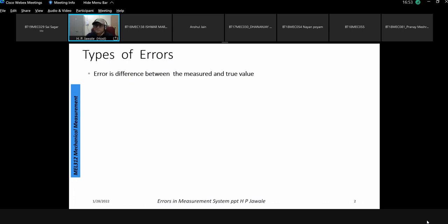So starting from that, there can be many mistakes or peculiar functions of the measurement system itself, which are going to cause error in the system. So first of all we try to find out, quantify and understand what different kinds of errors can be present in the measurement system itself. What we studied in the last class is a gross way of defining the error: the difference between the true input, the true value, which is always in question because we do not know the true value at any instant of time.